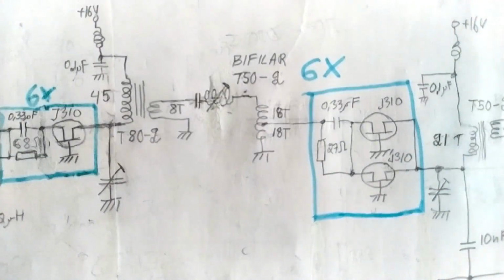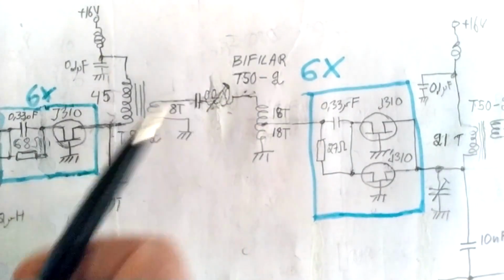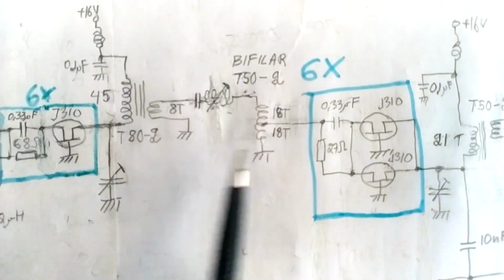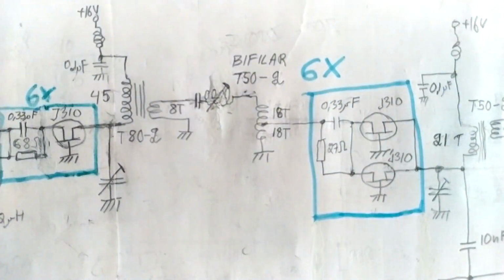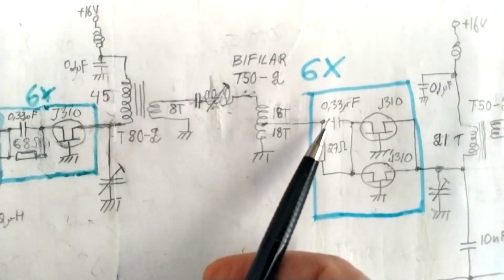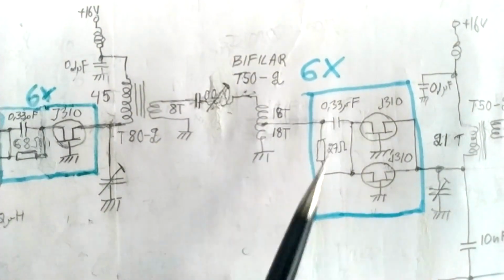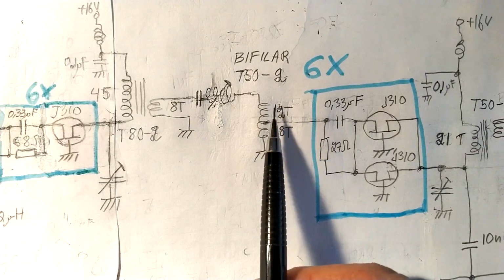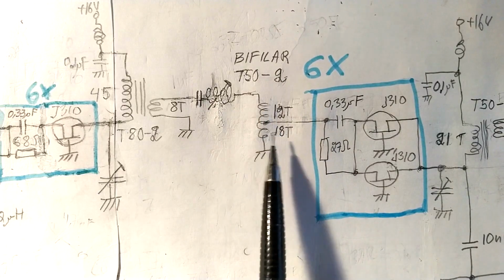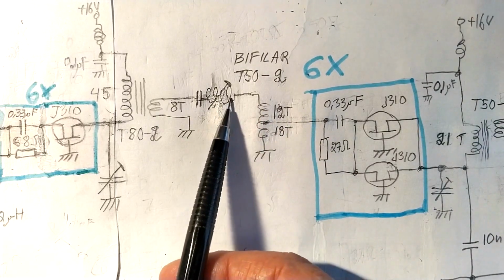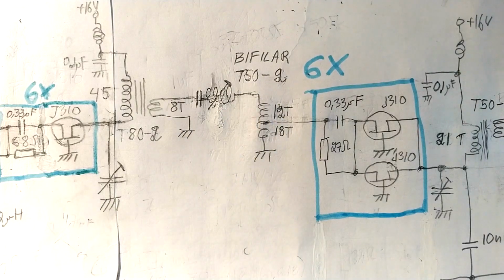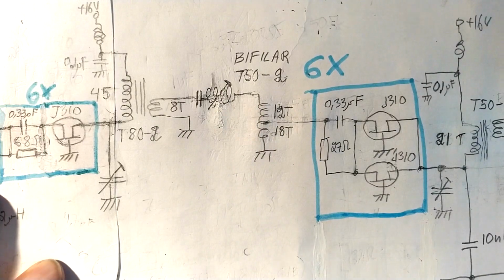The impedance into this point is 16 ohms, and this is a transformation of factor 2 of voltage, means 4 of impedance. So it means I have 4 ohms in this point. I have changed the turns ratio, removing a couple of turns here. That makes the impedance lower in this point, about 11 ohms now. And then I have tuned the unit properly.